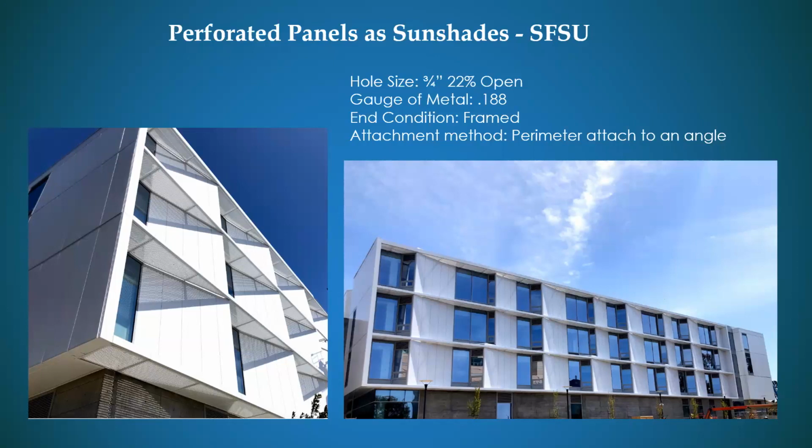So when we get into design assist, but certainly when you get into the shop drawings, you want a manufacturer that is not saying, oh, well, maybe they should have thought of this or that. You want to make sure it's clearly shown on your shop drawings how these panels are to be attached, in a fashion that the installer can actually achieve what's drawn on there. And a lot of that went into this piece as well.